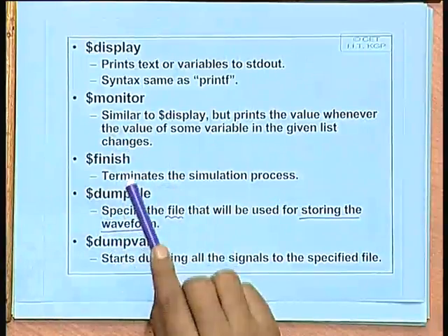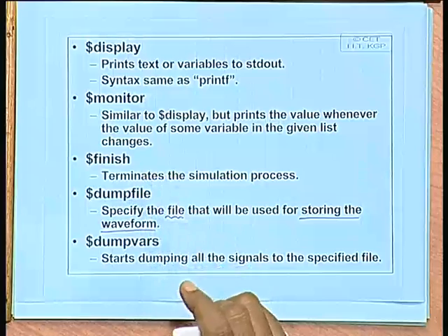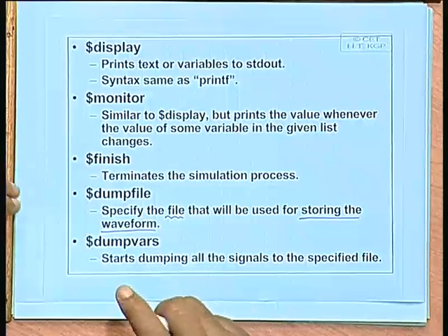Dump vars and monitor and all these will be only with respect to that particular module in which we give this, that testbench module that we are using. Not outside that. The scope of this will be only within that module. Right. Okay.